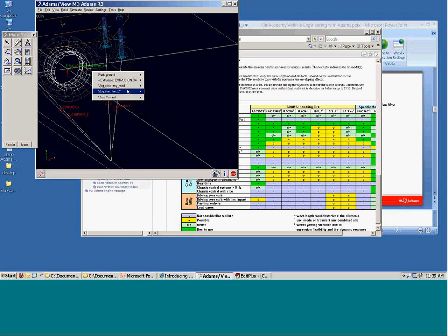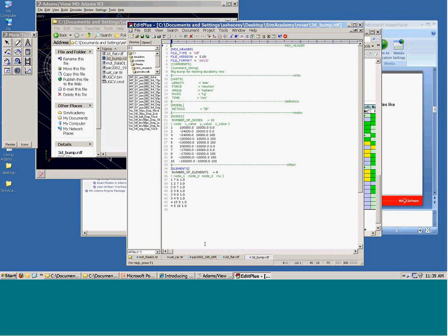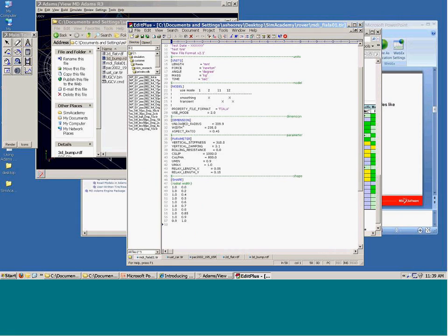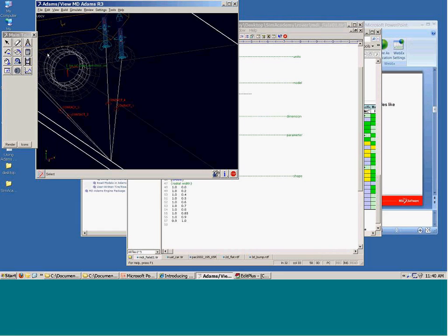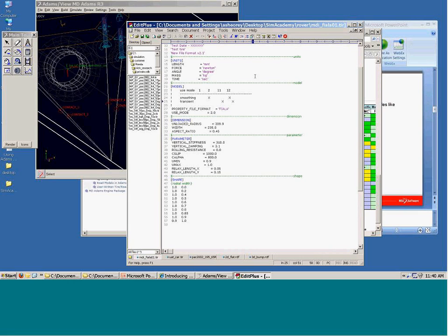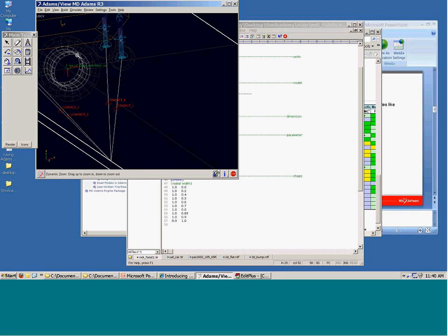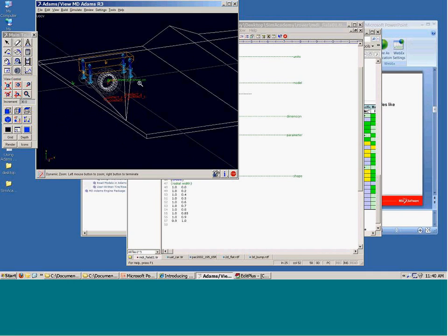The tire property file being used here, which is this one, is the one that gives these graphics here. So again, these are just graphics, not really needed, but they do look good. So you can create a model wherein you started off with rigid contacts and replaced them with pneumatic tires, based on whatever tire test data you have. Is that clear so far?